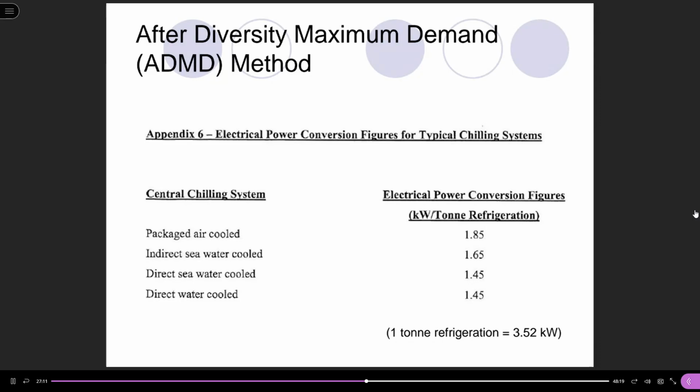All right? So what should be the power factor? The smaller the power factor, the larger would be kVA. We have a particular kilowatt divided by power factor, then we have kVA, right? And the power factor is a number smaller than 1. So the smaller the power factor, the larger would be the kVA. So we may use the smallest expected power factor, which would be 0.85. Okay, in a low voltage distribution system, 0.85 is the lowest power factor.